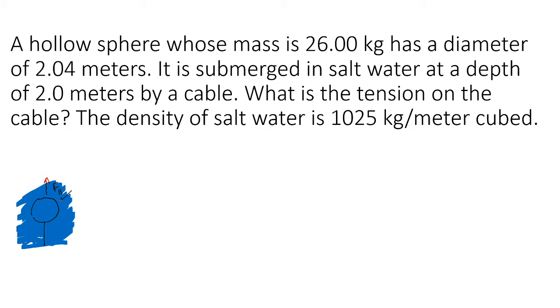In a liquid, we know that pressure comes in from all sides. And that pressure wants to push that sphere up. And it's just going to keep pushing up, pushing up, pushing up. Now, if we tethered that to the ground, you know what would happen if you took a pair of scissors and cut the string of this ball, it would go shooting up in the air. We've seen that before. So the tension and the weight of the sphere are going to be holding it down, and the buoyant force is what's going to be pushing it up.